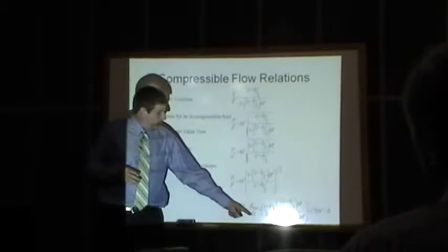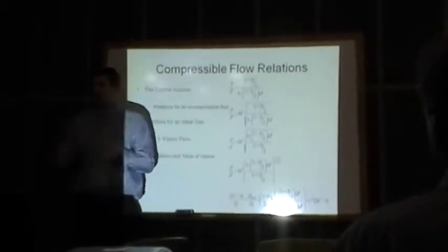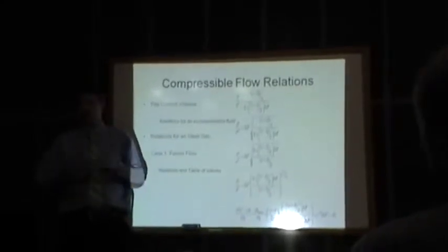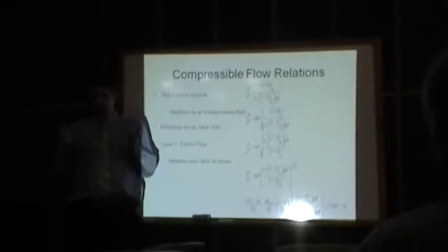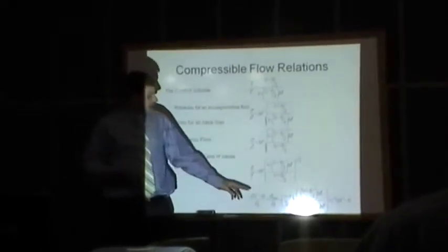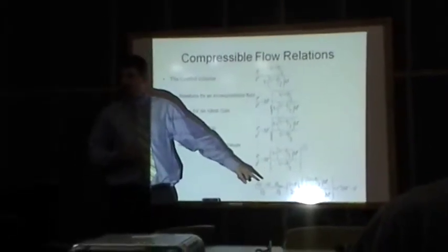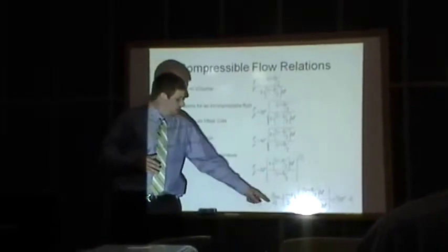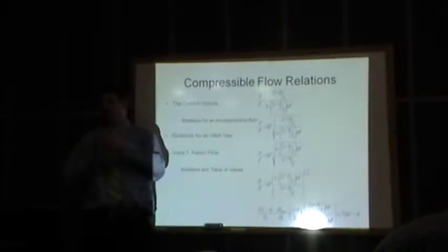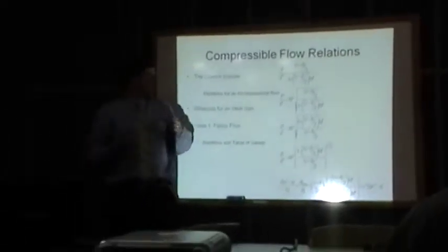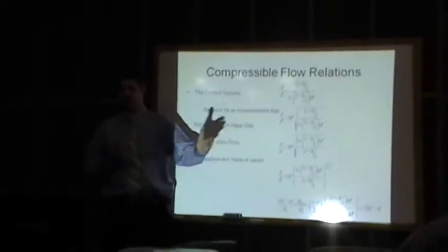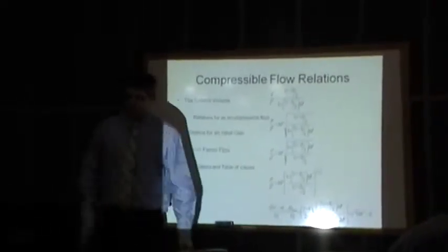Now this fL max over D, for my specific case, was at a value of 0, and that happens because in my model, the change in pressure was so great that there was a choked flow condition at the end of each tube. Therefore, I could then back out, okay, if I just have frictional pipe flow, what speed was it at the very beginning entrance, and then I could look at all the properties as it moves down the pipe.